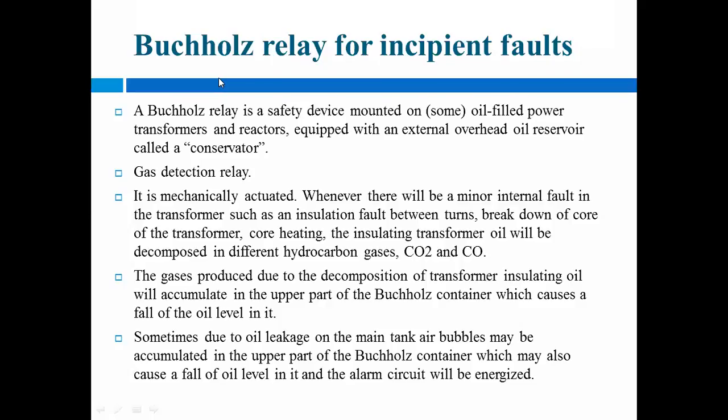This relay is a gas actuated relay. Gas actuated relay means what? When any fault occurs in the transformer, suppose an insulation breakdown or a core fault, sometimes the oil in the transformer gets reduced. When such a fault occurs, some gases are liberated from that oil.